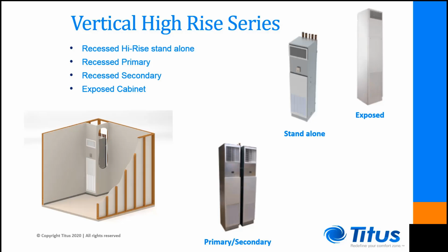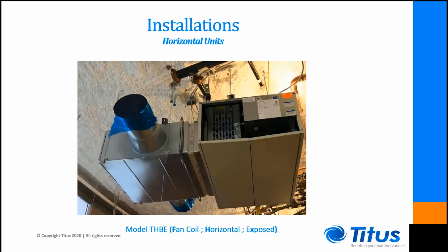The vertical stack unit gets its name in that it is popular in tall, high-rise buildings. The units are, quote-unquote, stacked on top of each other from floor to floor all the way up the building. A vertical stack unit on one floor can have its plumbing attached to the unit on the floor above it over and over again all the way up the building. This reduces project site plumbing work requirements and overall installation costs.